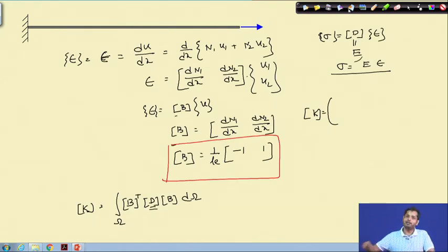Once we have the nodal load vector, then we can apply the boundary conditions exactly the same way we applied boundary conditions in the matrix method. And then once we apply the boundary conditions, we can partition the stiffness matrix and calculate the unknown displacements exactly the same way we did it for the direct stiffness method. Once we have the unknown displacements, the rest of the process is exactly the same as in that method.